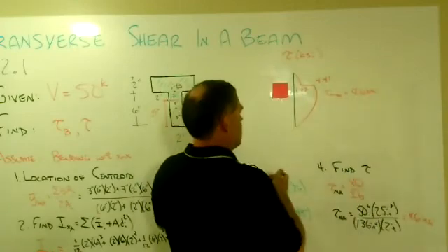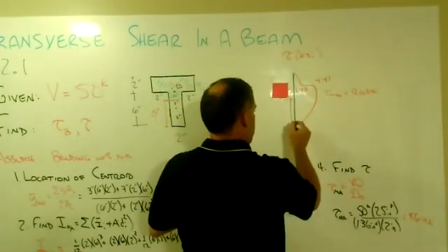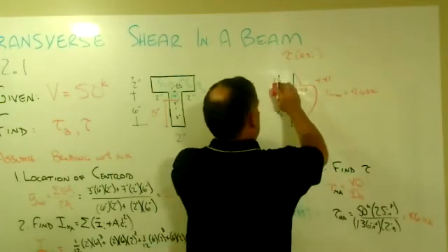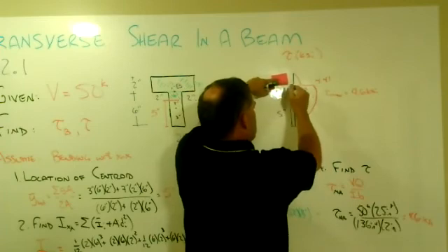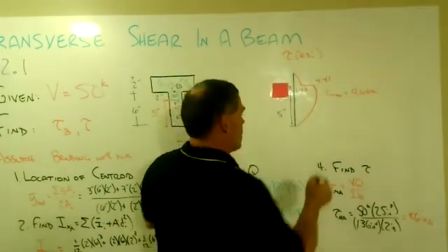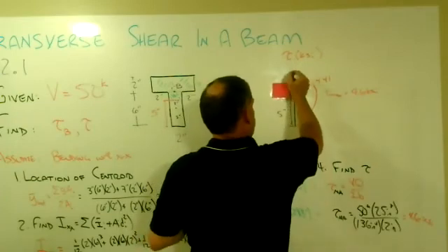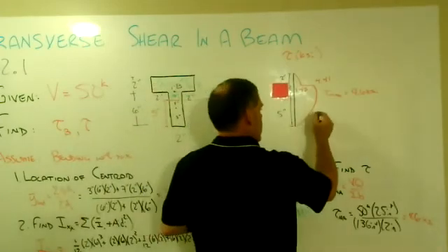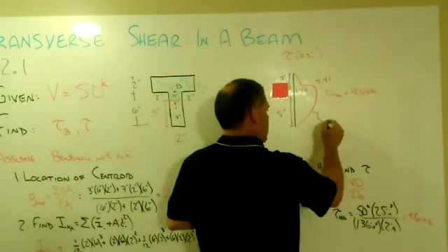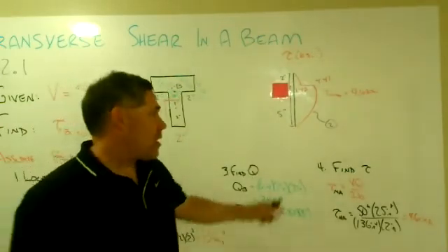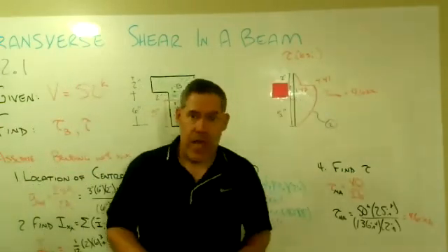And the distances that we're talking about here, that would be 5 inches off of the bottom. And then we got another 1 inch here. You probably noticed you got a glare there. That's why this whole thing is there to begin with, right? So that's a 1 inch, and then we have 2 inches up to the top. And again, this is second order variation. 0 at the outer and maximum here at the neutral axis.